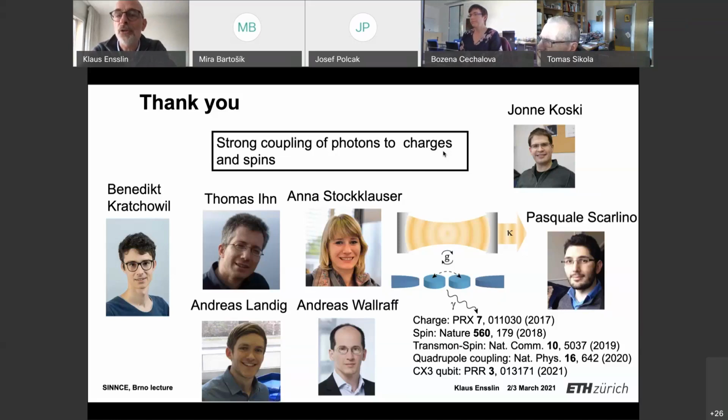It means that's where you can make nice resonators. Also, you have good amplifiers. And amplifiers have been mostly developed in the field of astrophysics because they also have resonances in that regime. So once you go above 10 gigahertz, it becomes complicated with cabling in the cryostat. So it's all doable, but it's not just adding a source that gives you a higher frequency. You have to change your entire setup.